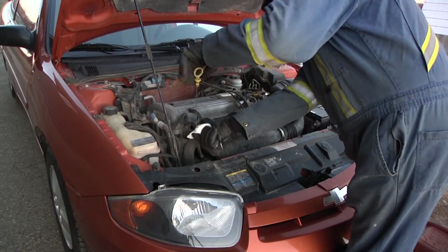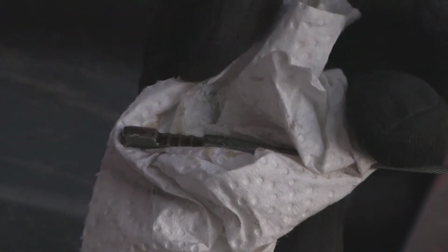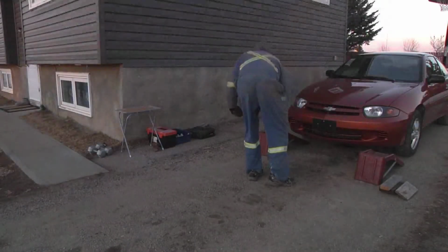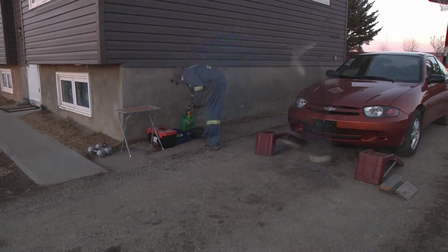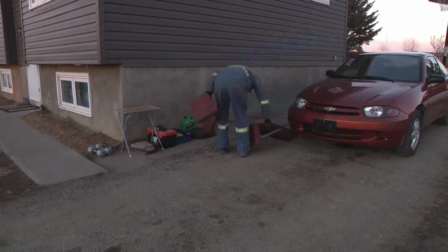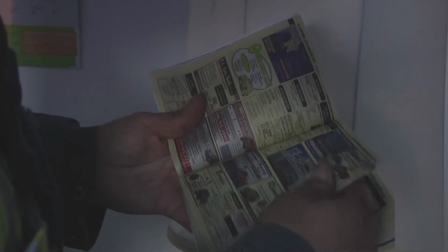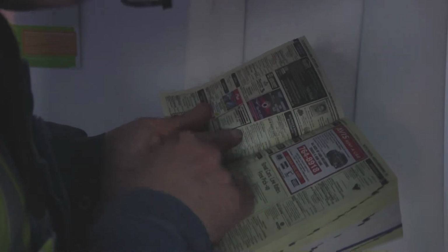Check your dipstick for oil level again. You should get an accurate reading now that the vehicle is level. We can clean up the area now by putting away our tools and cleaning any remaining oil spills that we may have missed. To dispose of your old oil, contact your local auto parts supplier or check the yellow pages in the phone book to find out how to properly dispose of your waste oil.